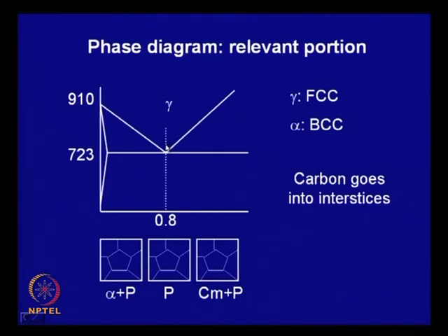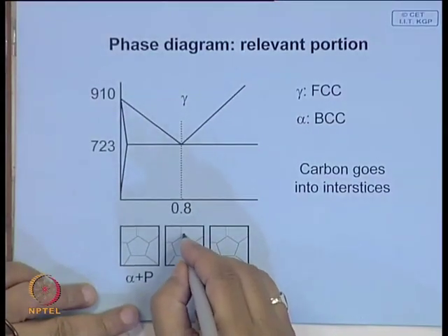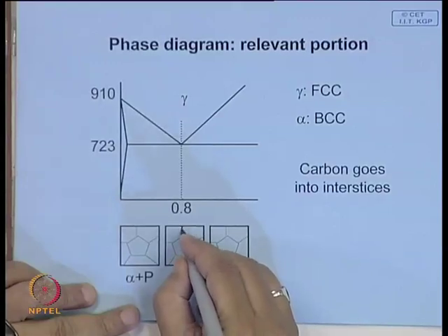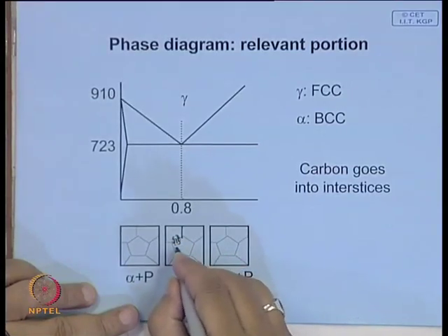And now we will try to see what type of structure will develop if you cool it under different conditions. And if you recollect this earlier diagram, this particular steel is known as eutectoid steel. If you remember that structure, when you cool this steel, you have pearlite forming, and pearlite is made up of alternate layers of cementite and ferrite. So, this is the way this pearlite forms. This is a nodule of pearlite. In that way, you will find a number of these nodules developing.